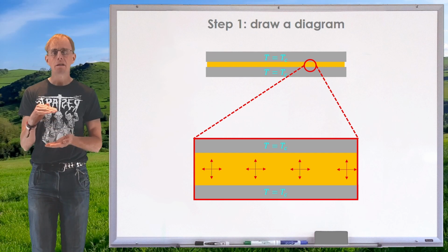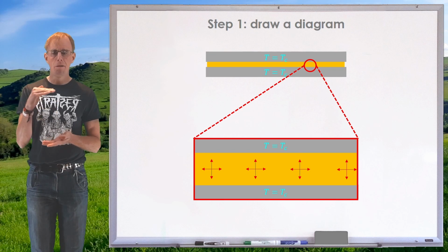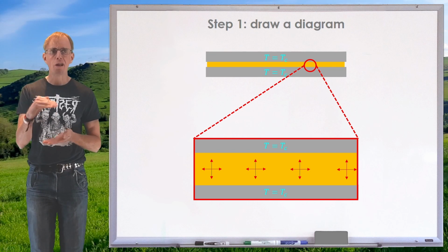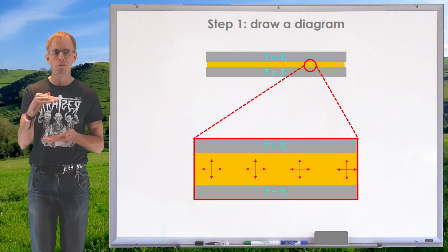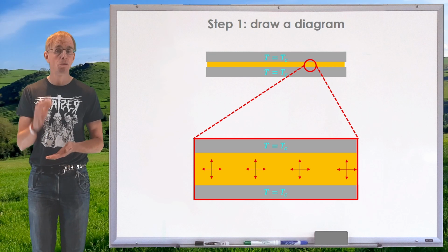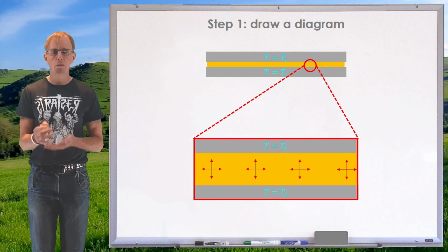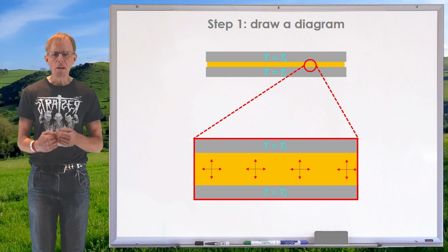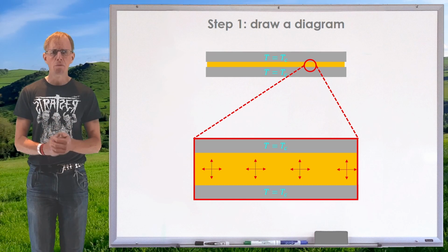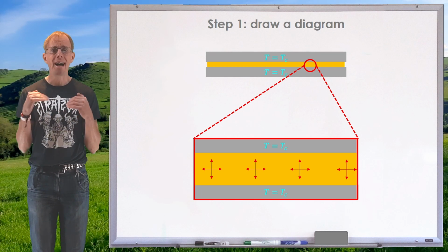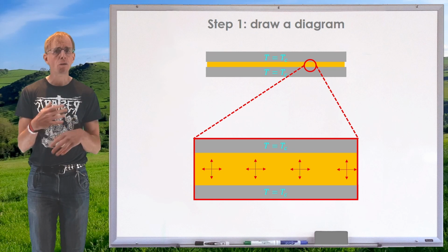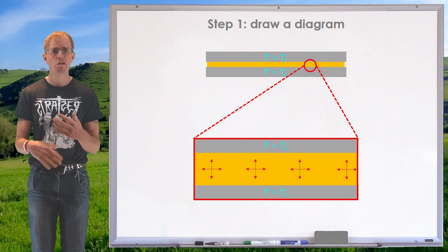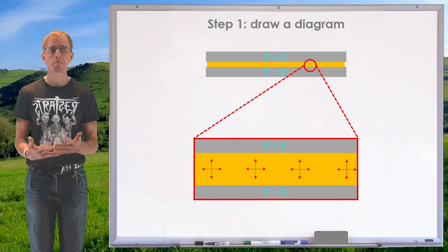We're assuming that we're cooling the material by imposing a change in temperature at the upper surface and at the lower surface, and that there's no contact resistance between the two. So there's no convection going on, but if we were to think about this, we're assuming that there's perfect heat transfer at the surfaces, kind of corresponding to a convection heat transfer coefficient of infinity.